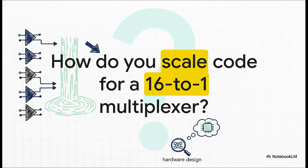So now that you understand the basic rules, the physical logic gates, and how to write that smart recipe for hardware using behavioral modeling, I want to leave you with this final thought. Think back to that super clean if-else statement we used for a simple 2-to-1 multiplexer. Knowing how clean and scalable that approach is, how effortlessly do you think you could scale that code up to build a massive 16-to-1 multiplexer? Imagine trying to wire that beast by hand structurally versus just writing a few intuitive lines of behavioral code. It really changes how you look at hardware design, doesn't it?